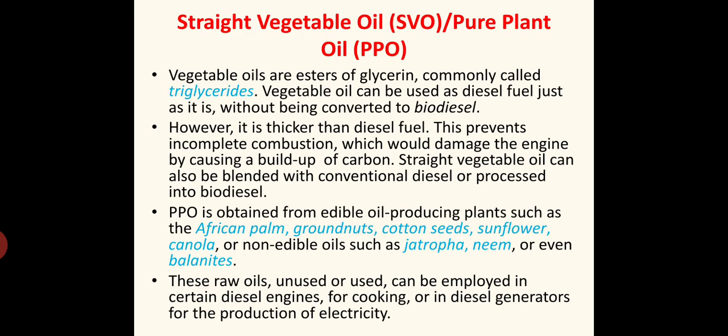Coming to the straight vegetable oil, SVO, or pure plant oil, PPO. Vegetable oils are esters of glycerin, commonly known as triglycerides. Vegetable oil can be used as diesel fuel. Oil can be used as diesel fuel just as it is, without being converted to biodiesel.